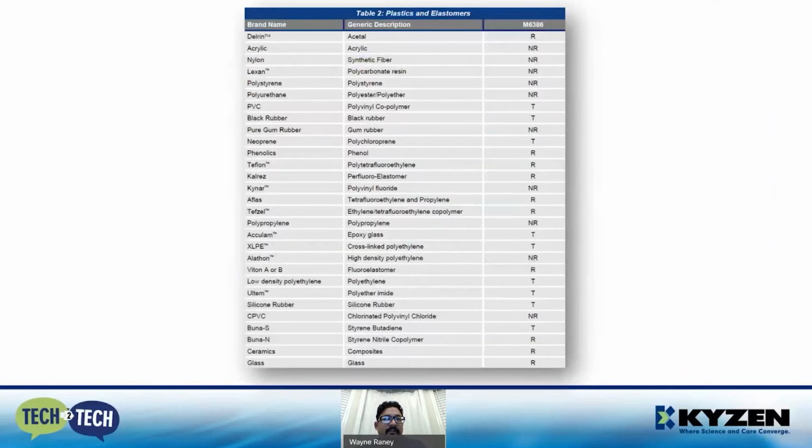As far as elastomers go, this is a list of materials that are recommended, not recommended, or require additional testing. Machine companies usually mainly use this list to make sure that the materials of construction are compatible with modified alcohol. If you're putting elastomers through the cleaning process, then we recommend you send the material into our lab for further testing of the solvent, as well as to address temperature concerns of the elastomers.